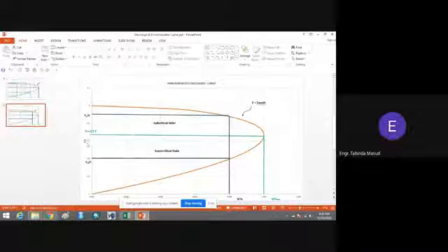You can see that this is 0.6, this is 0.8, and YC is somewhere between these two terms. So YC is always equal to 0.6 times specific energy head, or you can say 0.7 times energy head, or you can simply say it is 2 by 3, that is 0.67 of the energy head.